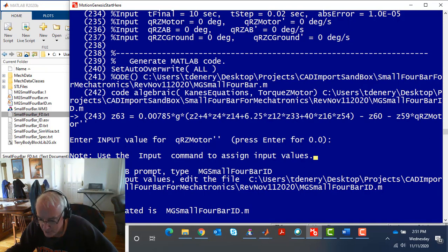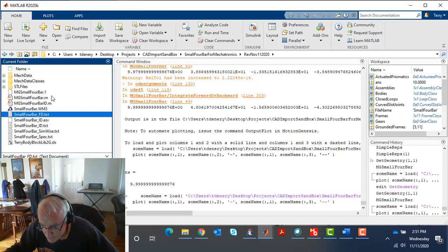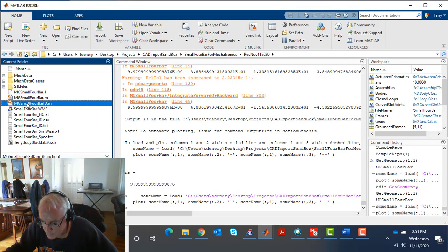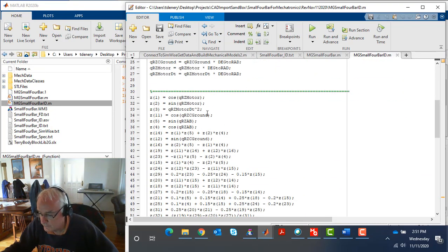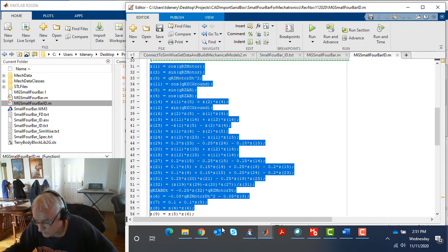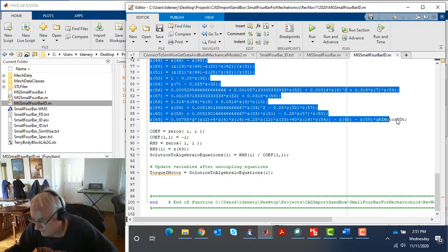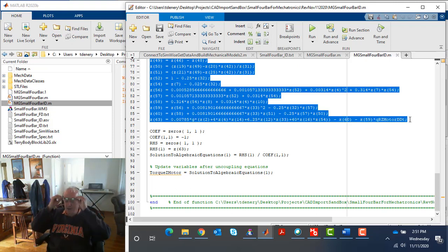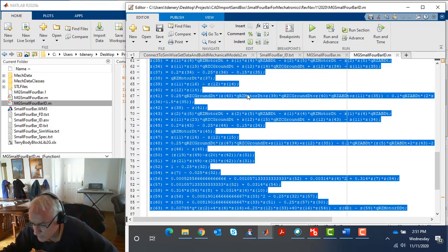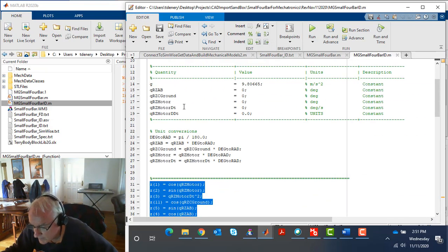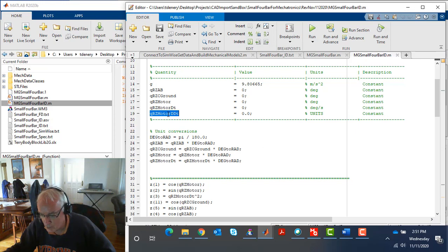And all I'm going to do now is finish by showing you the new MATLAB function that was created. This is real close to what we put in, and you'll see one of the things is that no longer do we have 98 algebraic calculations for this whole Z array, it's down to 63. So there's absolutely been this reduction. And I guess we see near the top that no longer are we solving or employing the second derivatives on anything other than the motor itself.